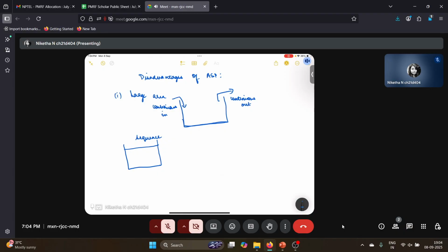This sequential batch reactor, or SBR, combines all the steps in one tank. For an activated sludge process, we need at least two tanks. One for the microbial reaction, where microbes will break down the organics and consume them. And a second reactor for secondary sedimentation, where the sludge will be collected. So these two tanks are required.